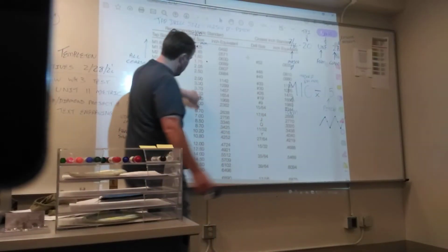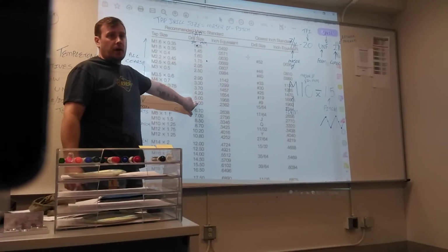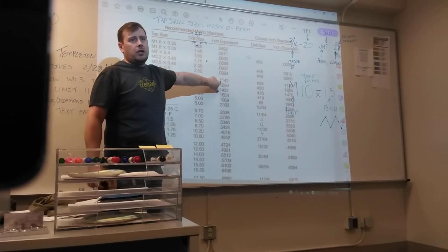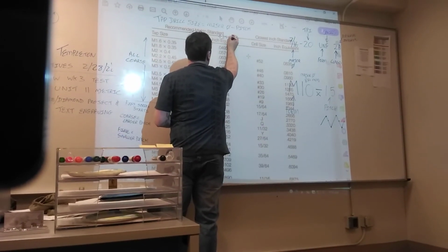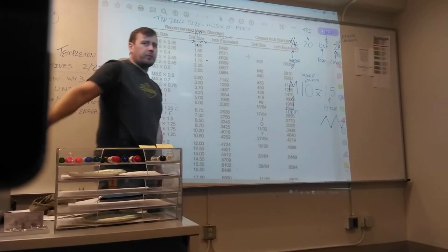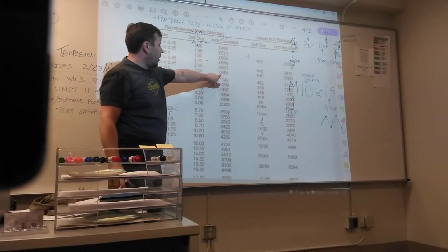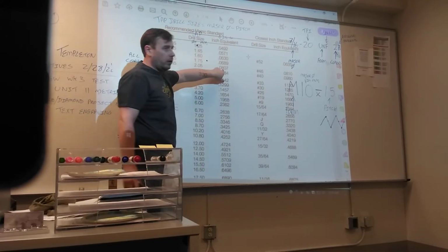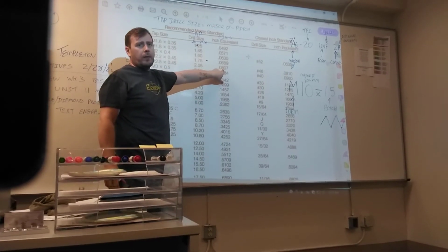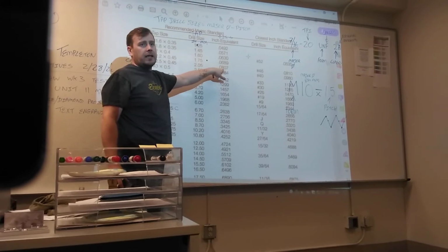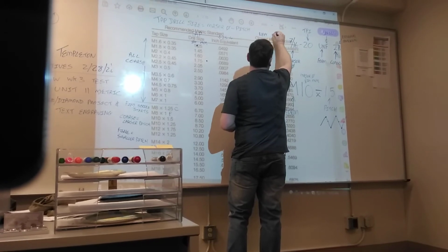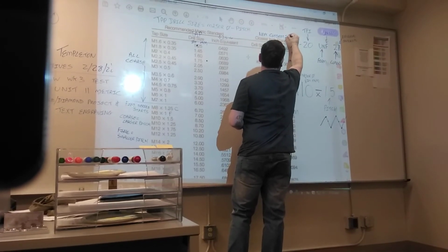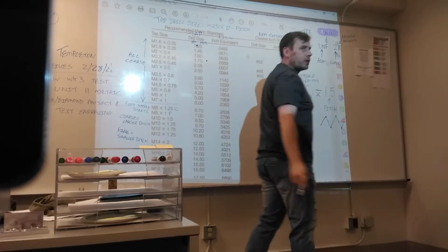If you take any of these numbers and divide by 25.4, you get the inch equivalent. So these numbers are just that number divided by 25.4. But what's the likelihood of finding a drill 80 thousandths and 7/10 in the shop? It doesn't exist. So these are the next closest size.